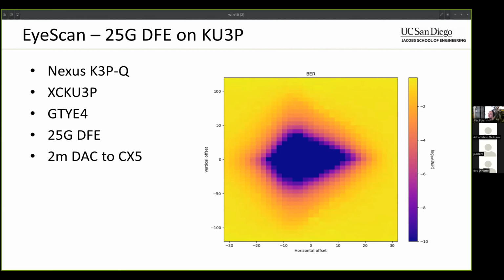It's like with the Intel FPGAs, particularly the Agilex, which is the only one I've been able to test in this mode. One of the issues I have at the moment is in 100 gig mode, for some reason, the soft logic in the E tile is not doing the transceiver adaptation loading properly. It's like something didn't get enabled that was supposed to be enabled. So it's only running with the default parameters. In 10 gig and 25 gig, it does load the parameters, and it does put the transceivers in DFE mode and adjust all the gains and whatnot.